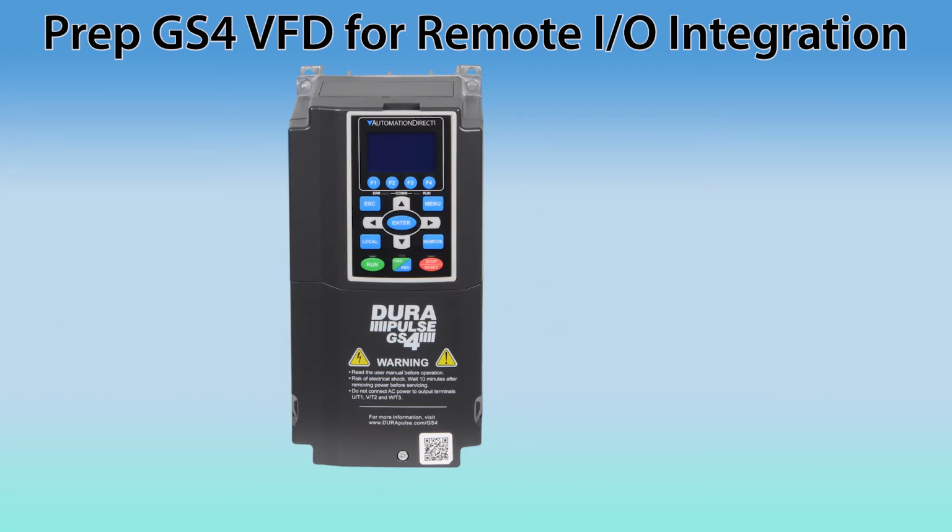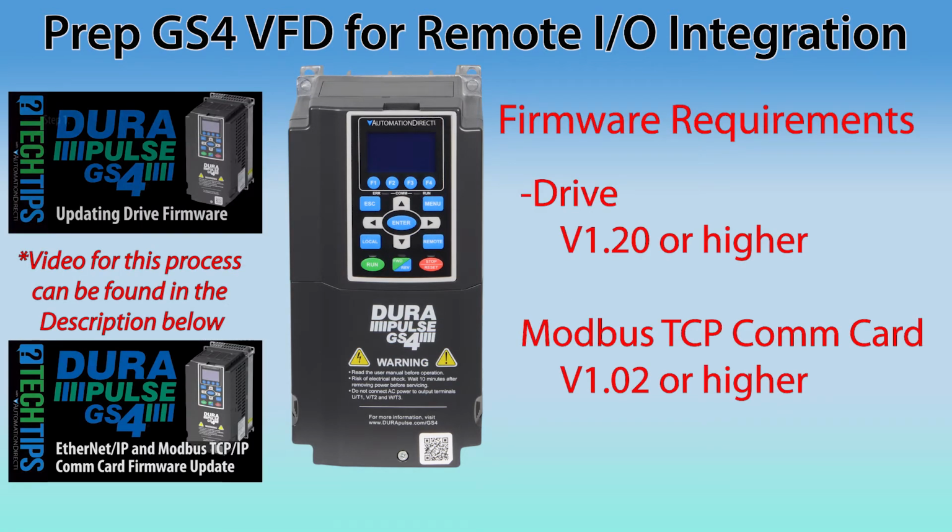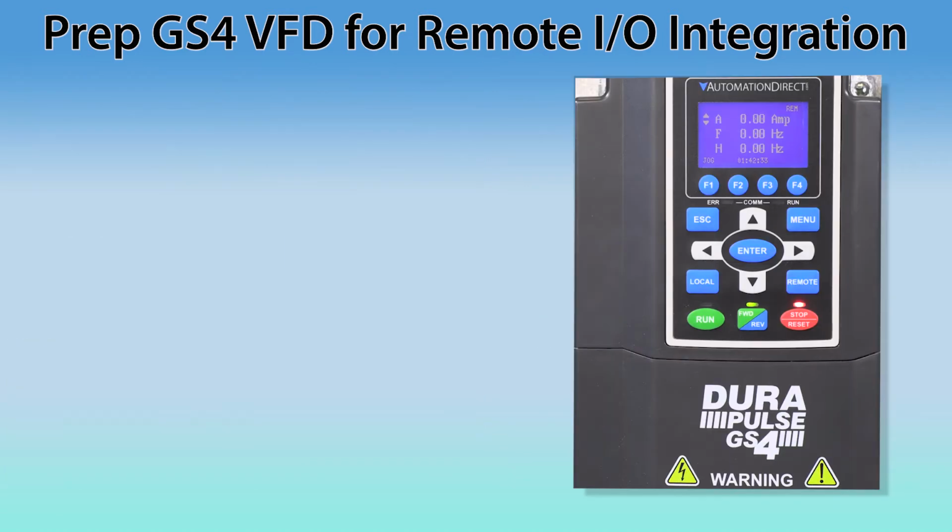To start remote I/O integration of the drive, you must have installed the Modbus TCP Communication Option Card. When you install this card, you will need to update the firmware on the GS4 drive and also on the Modbus TCP Communication Card. Once you have that complete, power up the drive, and let's verify that the Modbus TCP Comm Card is available on the drive.